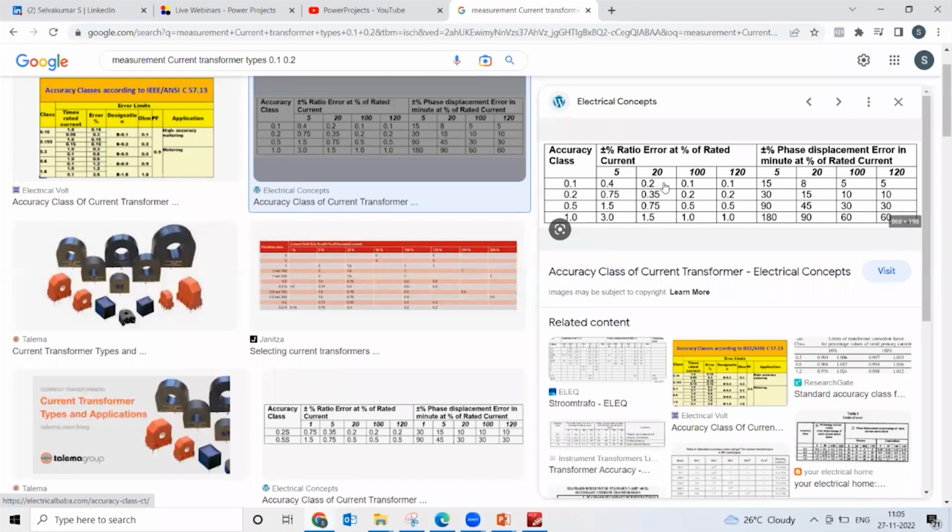And you will be specifically facing this problem in most places. Multiple examples: solar plants during night. The CT ratio should be selected in such a way that it's higher than the rated current. But during night time, the auxiliary power of the solar plant could be like 0.1%, which means definitely less than 5%, right? So obviously there is no accuracy guaranteed. So it's one really tough challenge.